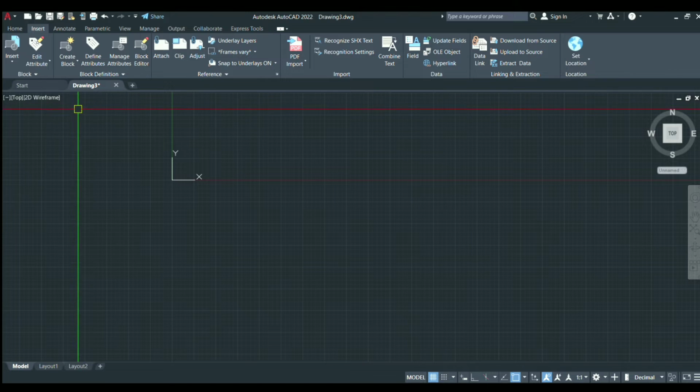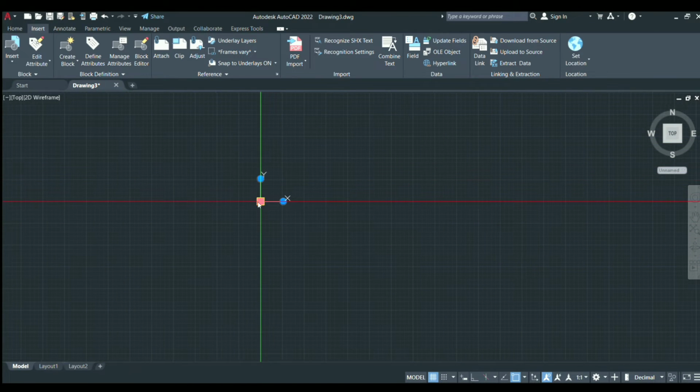So next, we have the user coordinate system or the UCS, which is the active coordinate system that represents the XY plane in 2D and XYZ planes in 3D. So here's the UCS or the user coordinate system, which we can move anywhere in the working space. It acts as the direction in the X, Y, and Z axis for drawing and modeling. We can control the origin and orientation of the UCS to make drawings according to the specific points and coordinates.